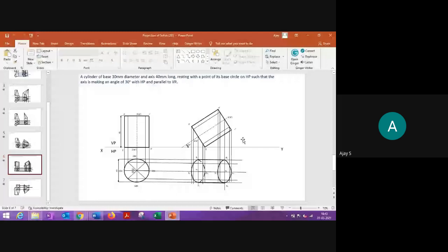When you are dividing it into 8, you need to divide at an angle of 360 by 8. For 12 divisions, we used to put 360 by 12, that is 30 degrees. Here 360 by 8 is enough. Okay, sir. So 360 by 8 comes to 45, right? So 45 degrees, you can just cut off and go.